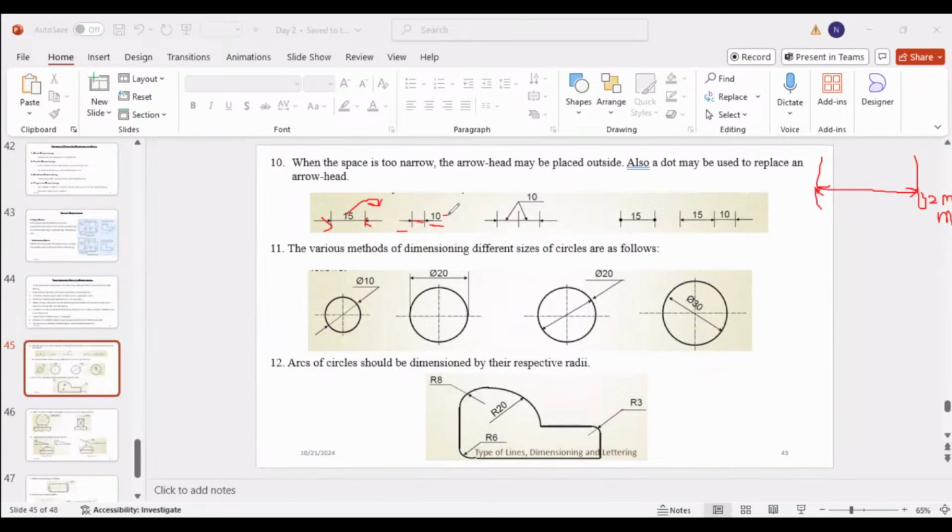You can draw it that way too. You can take the value outside in narrow places. Okay. So in here you can see that there are two equal lengths. So then you can mention that somewhere like this as a note and then you can draw two leader lines to these two lines, because there are two with the same length. Then, instead of writing 10 and 10 at both places, you take 10 up as a note and connect it to those lengths with two leader lines.